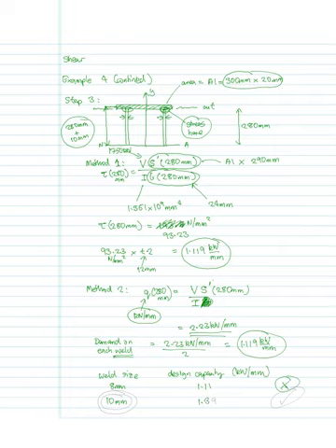And you can see that the 10 is 1.39 kilonewtons per millimeter. That is greater than 1.119 kilonewtons per millimeter. So you would choose a weld size of 10 millimeters, because that exceeds the demand on each weld of 1.119. So the answer to the question would be to choose a weld size of 10 millimeters. After this I will go through the calculations in a bit more detail.